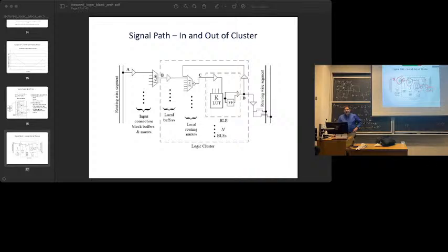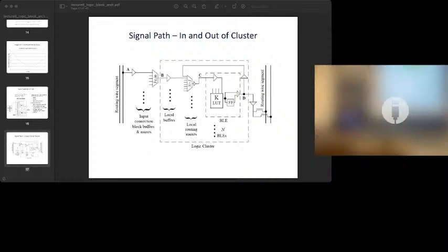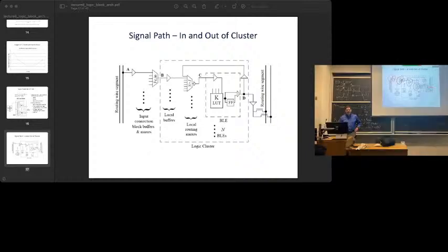Yeah, so you don't put this in your benchmark circuit. This is the electrical design of the FPGA. It's basically to isolate capacitance in order to improve speed at the cost of area. The reason this particular one, it turns out you need quite a lot of these inverters mixed in with the general routing wires. That turns out to be hard to do, and it's not a great area delay trade-off. Does that make sense? But the rest of this is pretty close to the way that the FPGAs that I know of are actually electrically built.